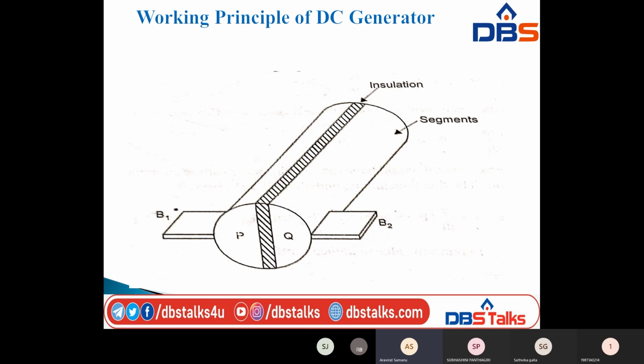So here I am taking one commutator. Why are we using the commutator? We have to convert the alternating quantity into a unidirectional quantity, that is DC. For that I am using the commutator. Here the EMF changes from instant to instant. At theta equal to 0 degrees, the EMF is 0. At 90 degrees, the EMF is maximum. At 180, the EMF is again 0.